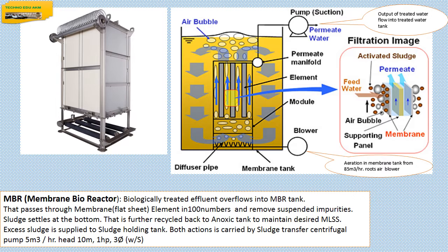MLSS abbreviates mixed liquor suspended solids value. Excess sludge is taken for drying and disposal through the sludge holding tank to the centrifuge, where poly is dosed for proper dewatering of the sludge. A chemical cleaning system is available for cleaning the membrane in the MBR tank.